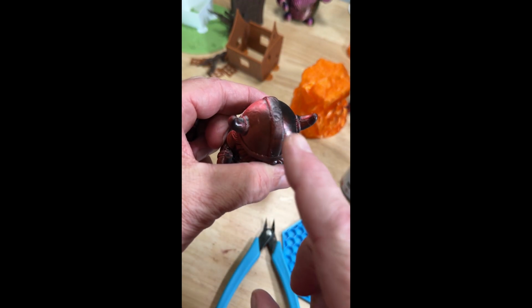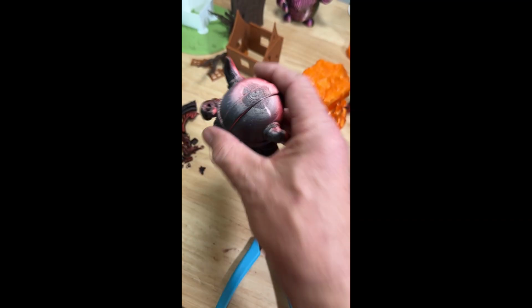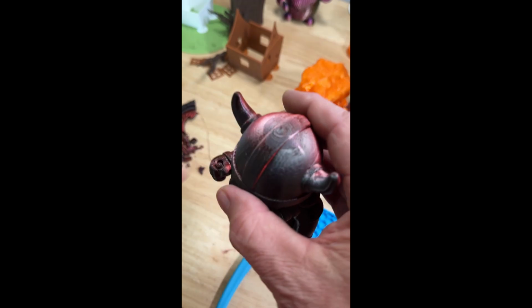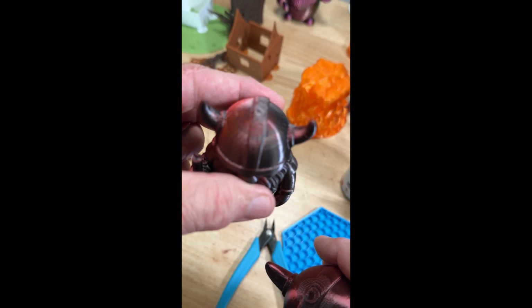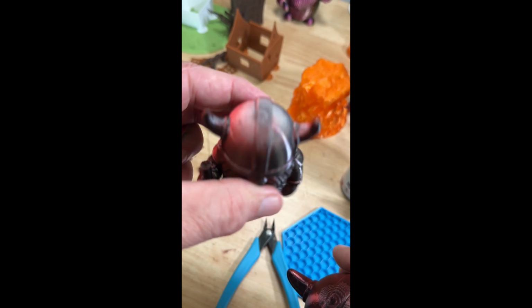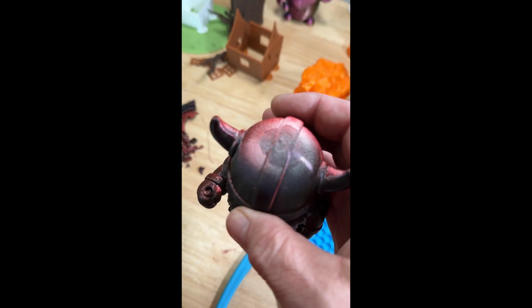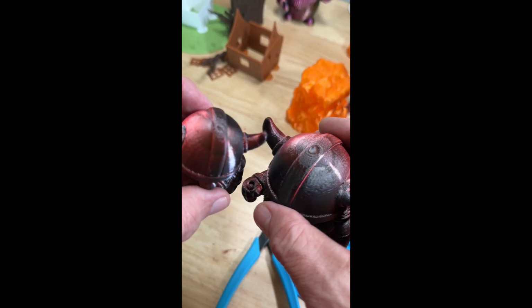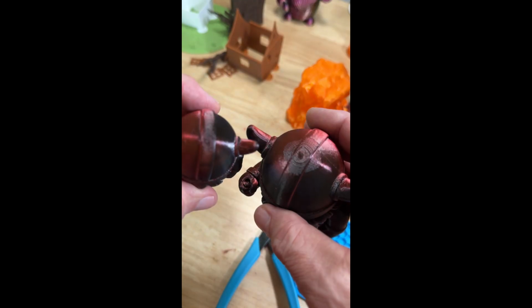But here's the thing I want to show: look at the top of this. Now look at the top of this one. This one I didn't change, I didn't modify the height. This one I did. And you can kind of see the change right about there if you look for it under the right light. But if you're not really paying attention, you don't see it. Now, I've tried adaptive layer heights, and I haven't had the success I've had by changing the actual layer height myself to a 0.12 for a small section.